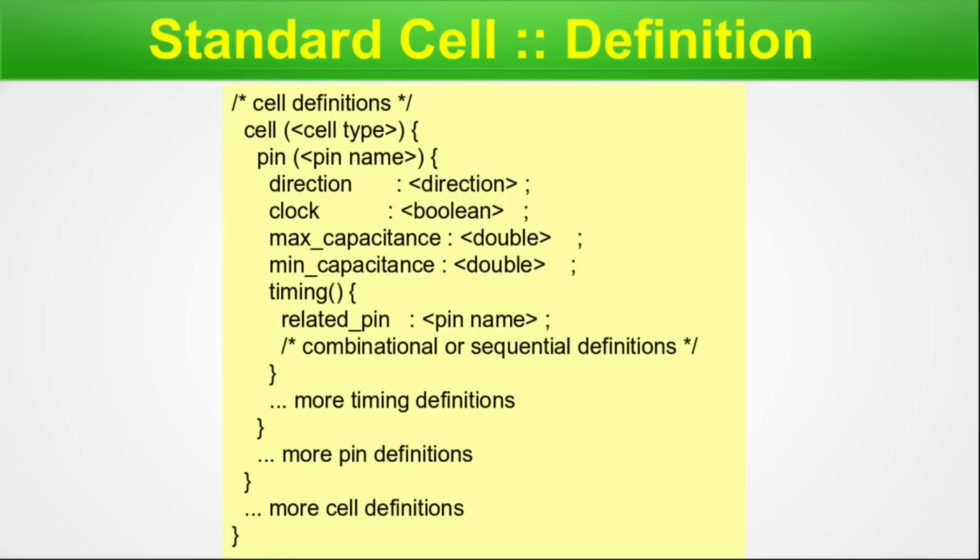So this is the kind of cell type definition, and this is a typical structure you will have inside the LUT. Whatever the cell type is, whether it's a logic family, or a sequential, or a latch, or a special cell, here will be the cell section. This is mask. One more thing not shown here is the functionality. This is a section that contains the truth table representation for combinational cells and the present state versus next state table for the sequential cell. This is well understood by any human eyes. We're done with this particular slide, so let's move on.